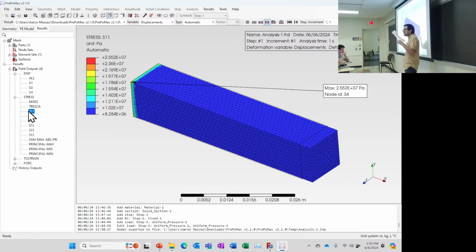What did I do on this left side? I said it is fixed. Everything is fixed: fixed x direction, fixed y direction, fixed z direction. It turns out in these models there are ways we can get around this to make it look more idealistic. For example, you can fix only one point on that left side, and then have displacement restrained in the x direction, because that's where you're pulling.